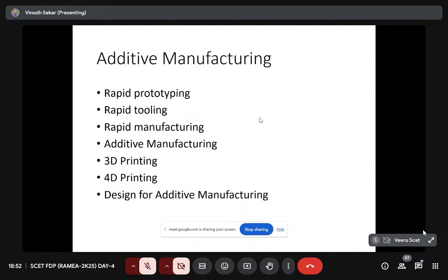So such modules are available, wherein we need to provide the geometric model or data of the component, and then we need to specify the materials, manufacturing process, and the manufacturer and user location, and accordingly the module will calculate the impacts across the life cycle phases like materials, manufacturing, use, and end of life, and we'll be able to interpret which environmental impacts are significant during which phase and how we can reduce the environmental impacts and so on.